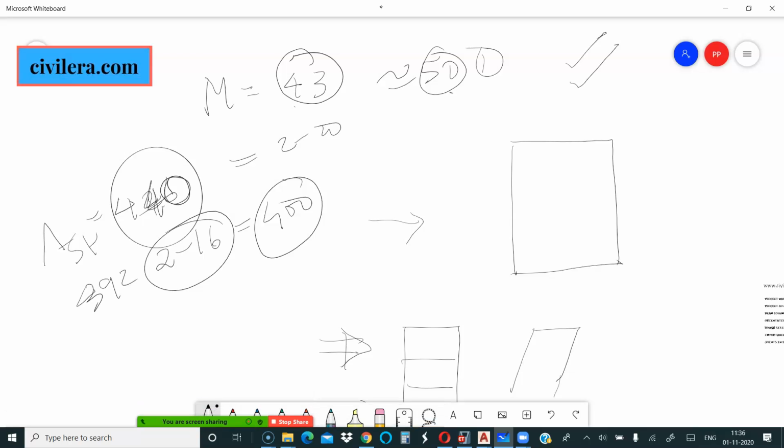If you want to apply your factor, I'm not talking about the factor of safety. That's always going to be there. What I mean is, if you want that increase or that cushion, always apply it in the end, and that end is the detail. So if you have given 212 and want to make it 216, take that decision at the last, not all through the process. That is duplication of safety. You have a margin in loads, a margin in moments, a margin in steel, and you again come back and increase the steel finally.